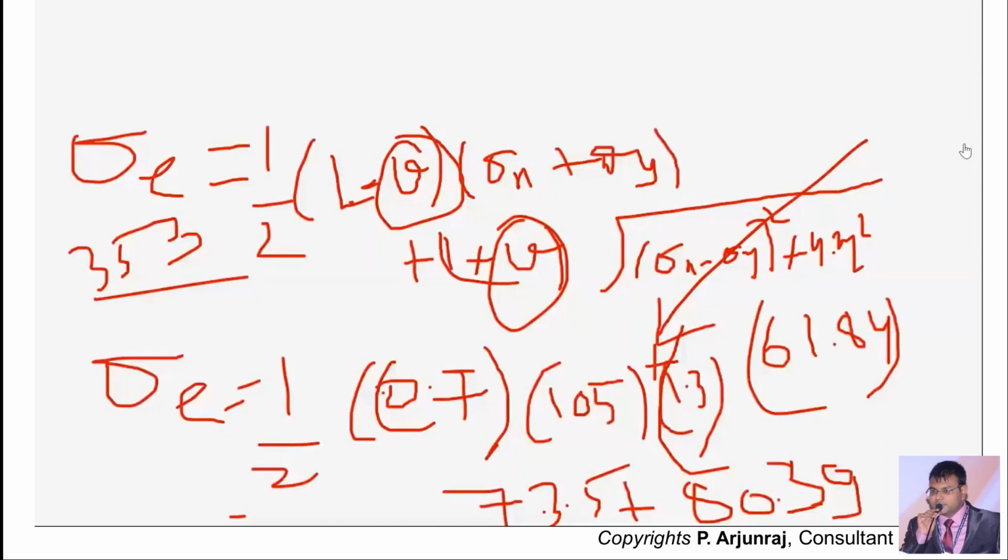When you are applying the load, with respect to the directions perpendicular to the application of the load, where you are going to get the measurement, which is nothing but the ratio of the lateral strain to that of the longitudinal strain. And this Poisson ratio, different materials will have different values. Here we have taken 0.3, and this Poisson ratio will range between 0.0 to 0.5, and again this will also vary with respect to different materials.